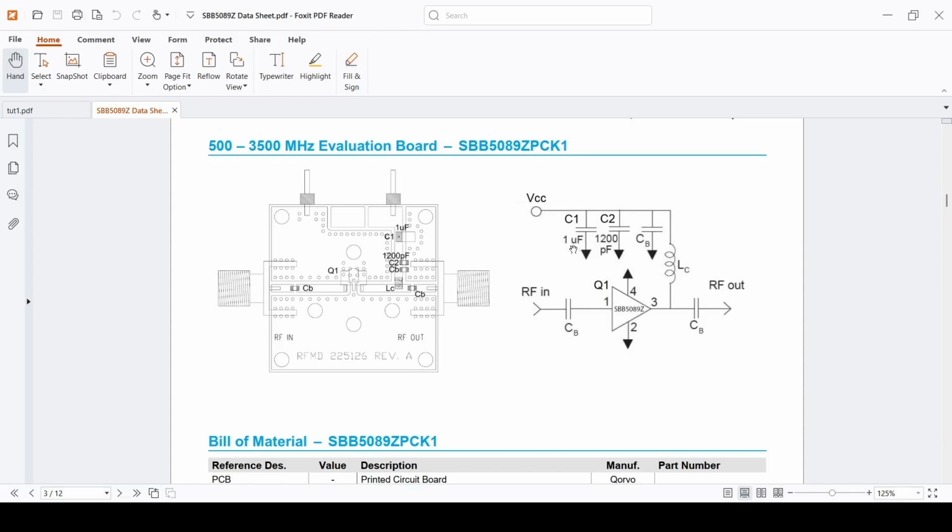Their parasitics increase, right? So ideally, you want a very high capacitor here, but when you increase the capacitance in components, all the parasitic effects come into the picture. You also see large resistances from the plate of the capacitor to the outside world or to the ground, which reduces the quality factor, or reduces the ability of the capacitance at higher frequencies. That's why in the design, we usually try to use multiple capacitors at different values.